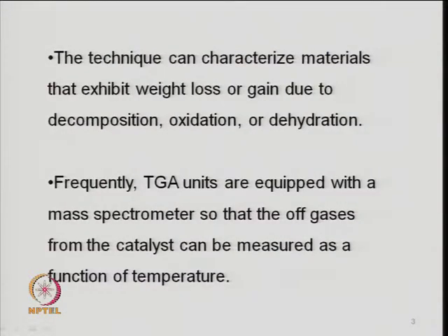So, this technique can characterize materials by weight loss or gain, because sometimes if you have a precursor of the metal and you have an oxidizing environment, it may oxidize also. So, during heat treatment you can have weight gain also. Depending upon that you can find out the delta H, which is related to temperature for a given weight gain, so you can find out the enthalpy of the reaction also. Oxidation, dehydration, decomposition of a material: the temperature required for oxidation, the temperature required for dehydration. These information can be obtained from thermogravimetric analysis, right.